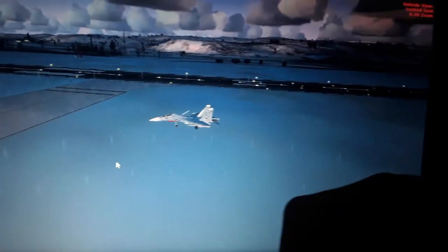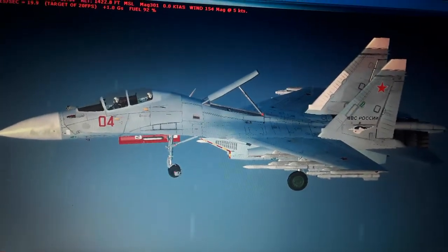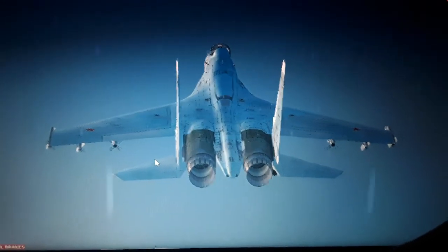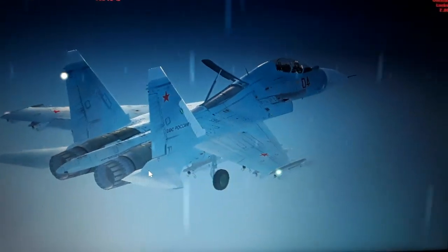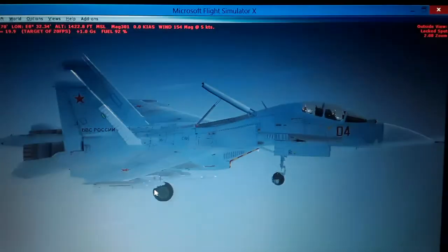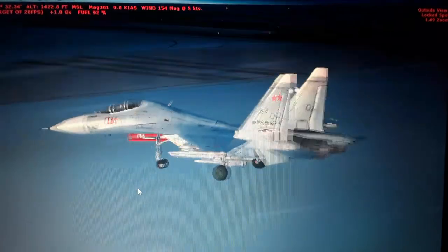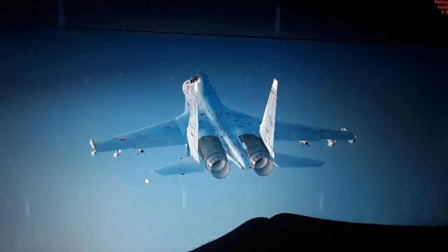You can see the slot, this speed brake extend. They retract over here. It's for slowing down the aircraft in the air and in landing. So we can retract this. Do this one now. So we also have the flaps. We need to extend. We have also auto flaps. Have takeoff. So here we go like that.